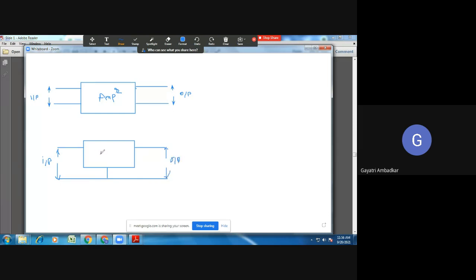And we call this an amplifier. This box is an amplifier. So you have to give input to the gate, output to the drain if you are studying common source amplifier, and source terminal is common. Am I audible clearly? Yes, ma'am. Source terminal is common.